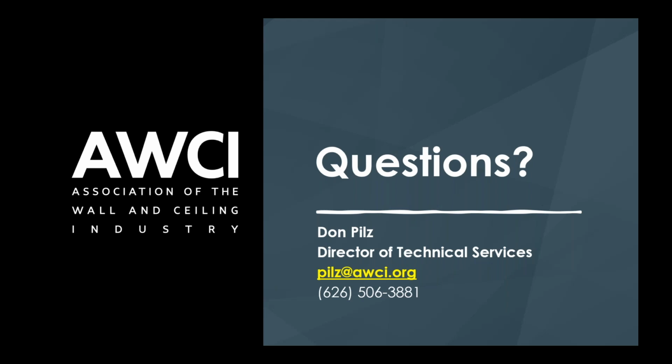Now, why that's such a good question to me is because I believe the way the test is ran is they just pour the water on top and 90% of that water has to make it through that drainage mat and get out. What I don't like about that is what happens when you stack a stucco system on it. And what happens if you start crushing it with stucco accessories? I don't think it's ran in a complete system. I think it's independently ran. So the manufacturer will make sure that they're in compliance.